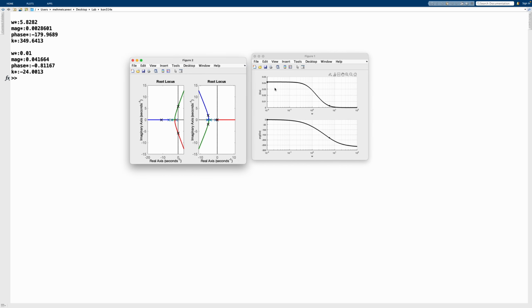But let me also remind you that the system has an overall gain here. And when the gain drops, we have something called the corner frequency somewhere here, which is going to be square root 2 divided by 2 times the original gain here. We call that the corner frequency. We can use this for bandwidth calculation and so on, but we can see that the amplification also tells us a story about the system. If we have high frequencies, higher than 10, it will basically get rid of the signal. It will reject the signal because it will be amplified with almost 0. So there will be no output whatsoever if you have the system as a closed loop.